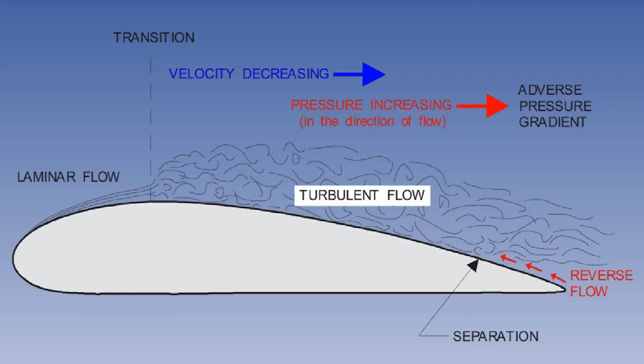It is worth noting that for clarity, the depth of the layers has been exaggerated in the diagrams. In reality, the laminar boundary layer is about 2 mm deep and thickens to about 20 mm in the turbulent flow.